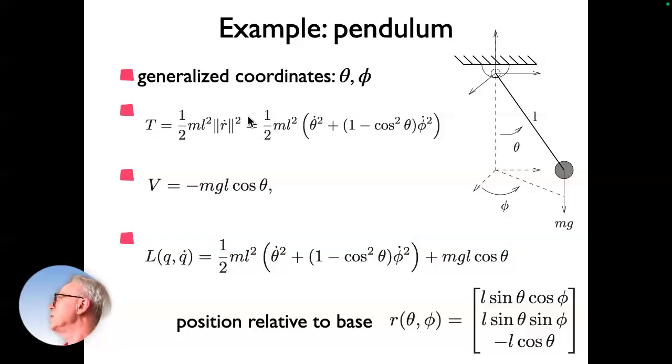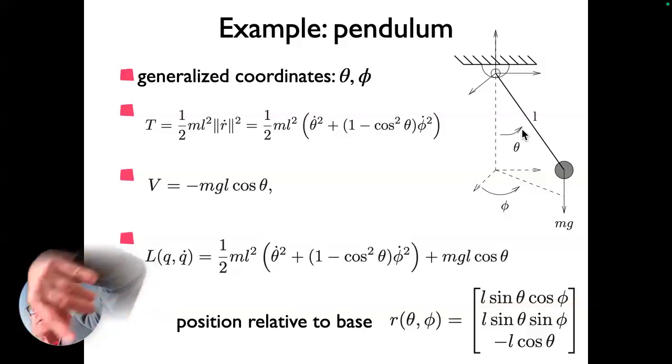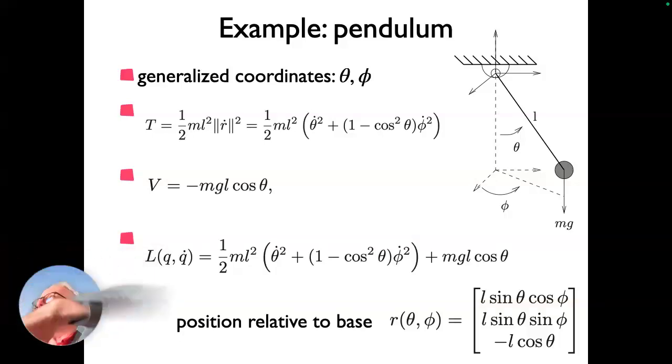And you have to take the inertial moment around, when this whole configuration, when the mass is all here, and this is the length of the rotating arm. So something you can compute, that's the inertial moment of that. So then you get this and that as the 2 contributions to kinematic energy. Somebody who knows these equations can write this down in like 10 minutes. And the potential energy just depends on this angle, right? If you're rotating in the plane, it doesn't really change the elevation. So just as you elevate this rope a little bit, then the gravitational energy will change.